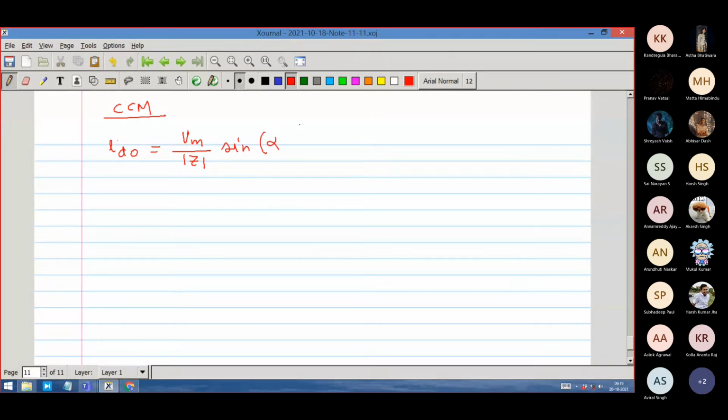It is always continuous, so the thyristor has turned on. The moment you fire, the thyristor is on. Minus tan inverse omega L by R, minus VDC by R, plus A e to the power minus R into alpha by omega L, right? This is what we had.